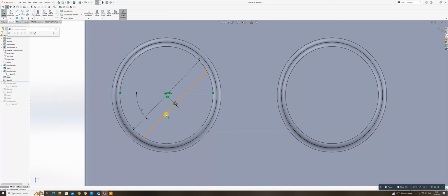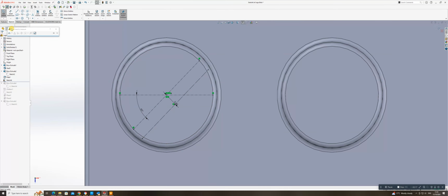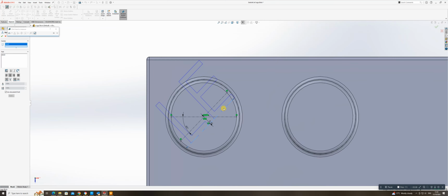And I'm going to change it to a construction line, and then you'll see the little A there. I'm going to pick up on that, and that's a little text tool. It's asking me to pick the curve or the line that I want to write on. So rather than that one, I'm going to pick the baseline on there, and I'm going to write the word Lego in capitals, and you can see it's way too big for what I want.